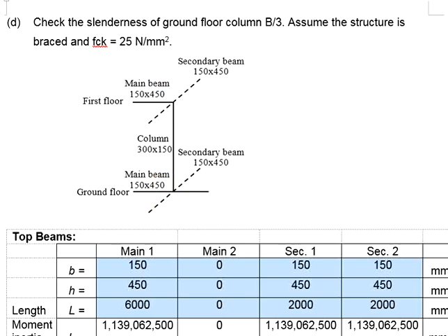Taking this as an example, you have moment in the major axis, and you have only one main beam from one side of the column. That leads to connections constituting of 1 and 2 members. Plus the upper column, you have only 3 members in the joint. When there are fewer members involved, the stiffness relative to the total stiffness of all the members joining together will be relatively high as compared to this end.